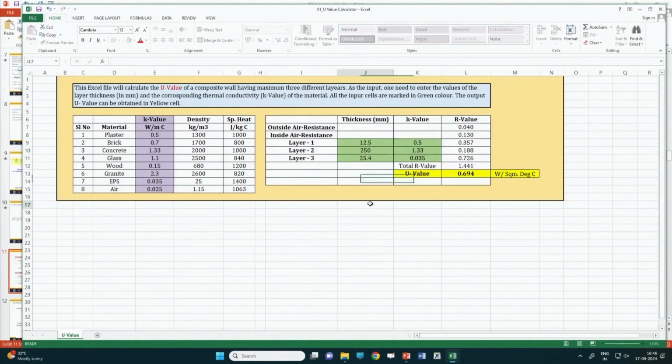On one side the plaster is 0.5 over here, and a 250 wall, and there is a 25 mm thick EPS. So, the U value is 0.9. Okay, suppose instead of the 1 inch, that is 25, I put 50 mm of EPS, the insulating material, it is again reduced to 0.55. So, I will share this with you, you can go through this.